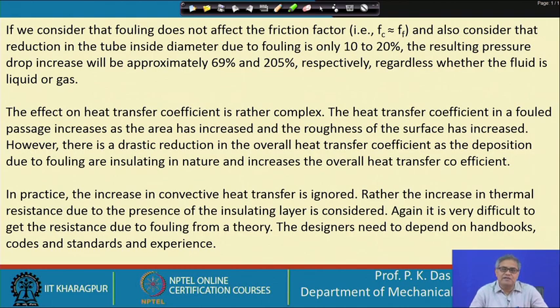Generally, in many of the cases, we neglect the resistance to heat transfer from one fluid to another fluid, the part of the resistance which comes due to the solid wall. That we neglect, because the solid material has got high conductivity and it is very thin, the solid metallic walls etcetera are very thin in many cases. But when there is deposition of foulant, the foulants are insulating material, their conductivities are low and the thickness can increase to some finite extent.